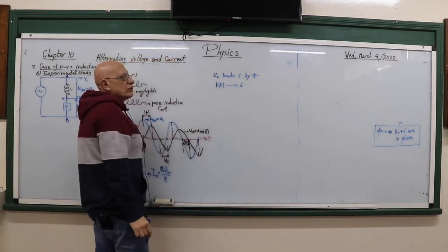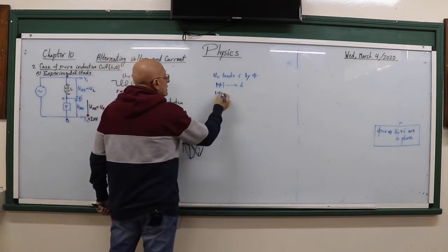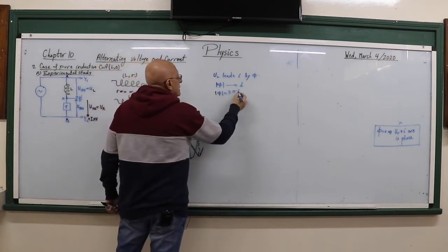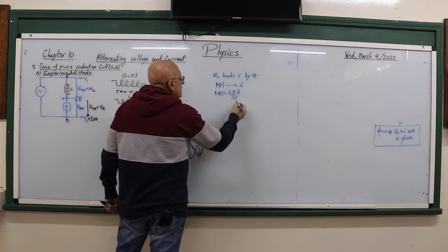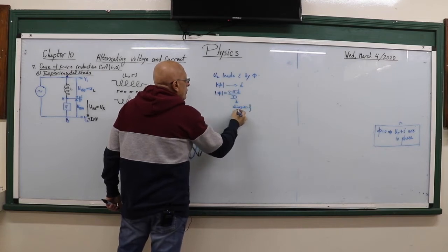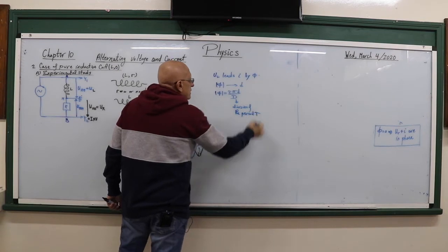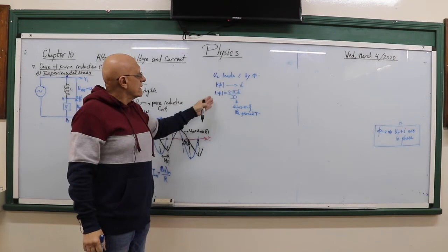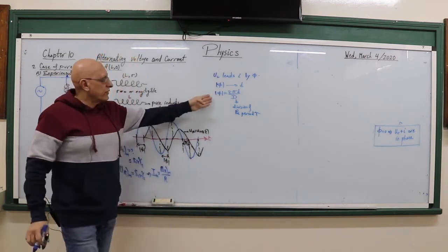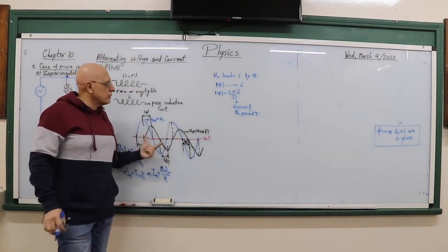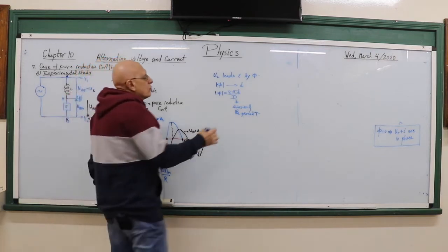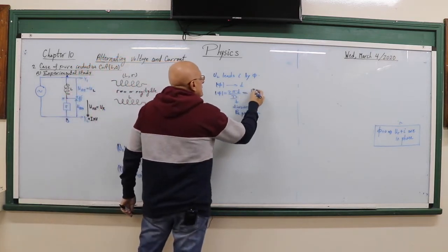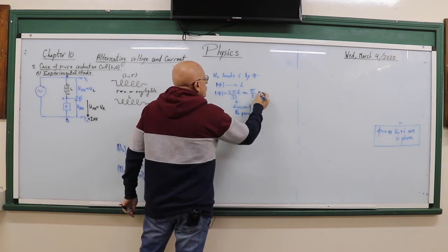I can change it to radians by using the following formula, pi d over capital D, where capital D is the number of divisions of the period T, and I explained this and proved it in the class. Now, if you apply this formula for this situation, we will deduce that phi is equal to pi over 2 radian.